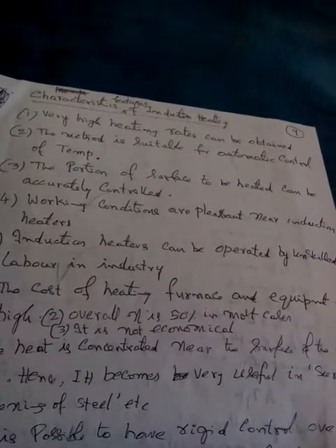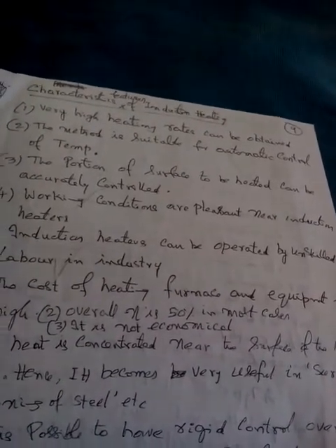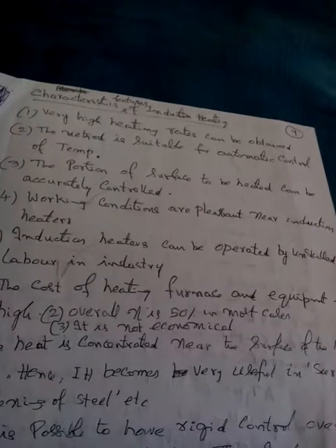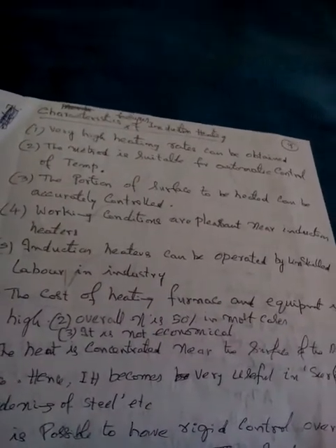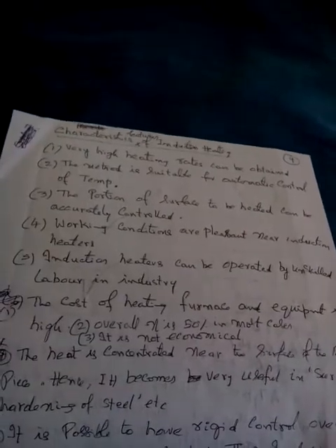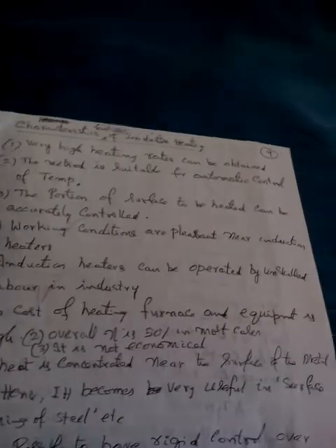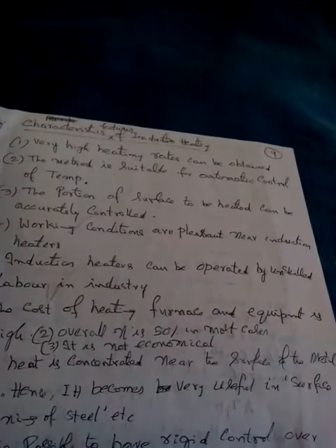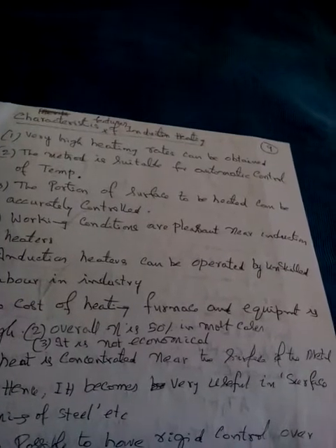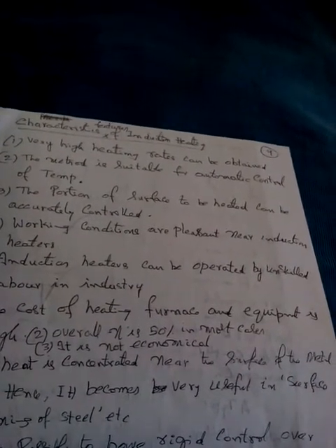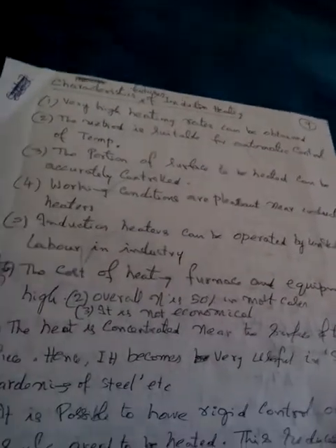Number five, induction heaters can be operated by unskilled labor in industry. So we don't require any skilled labor. Number six, the cost of heating furnace and equipment is of course high. Overall efficiency is 50% in most cases. So that's why it may not be economical, because 50% of the heat produced is wasted.